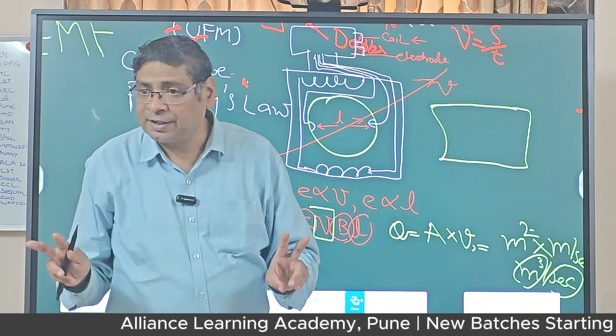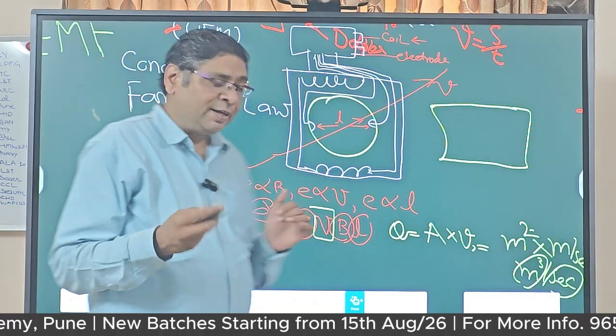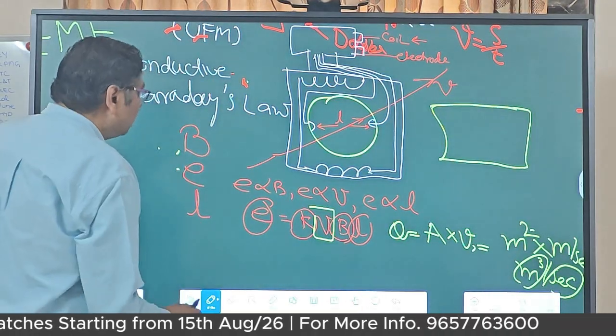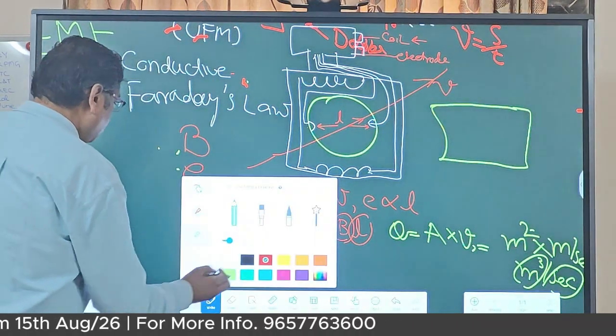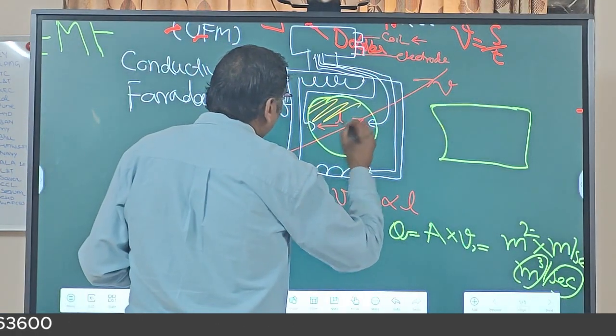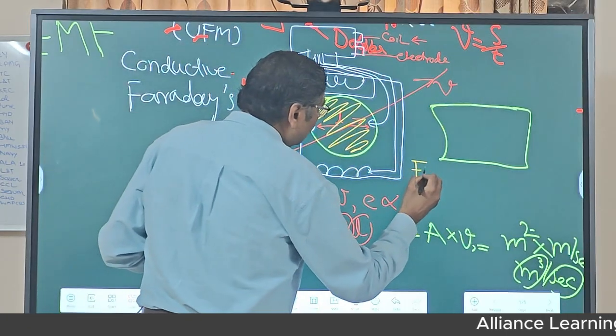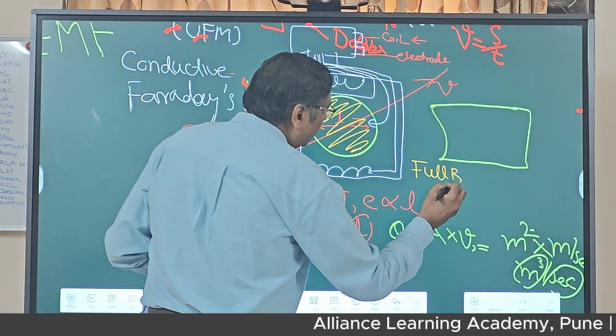Now two important things. One is the fluid should be conductive, and the second very important thing is that it should always be full bore. Full bore.